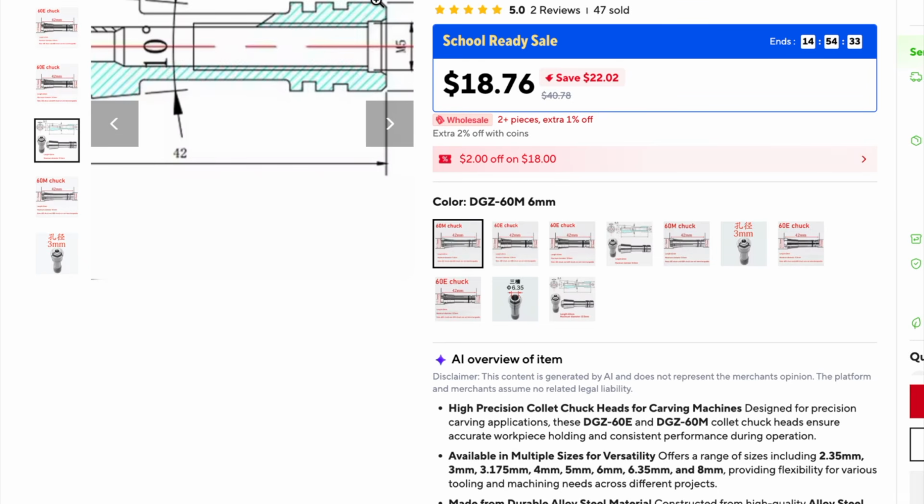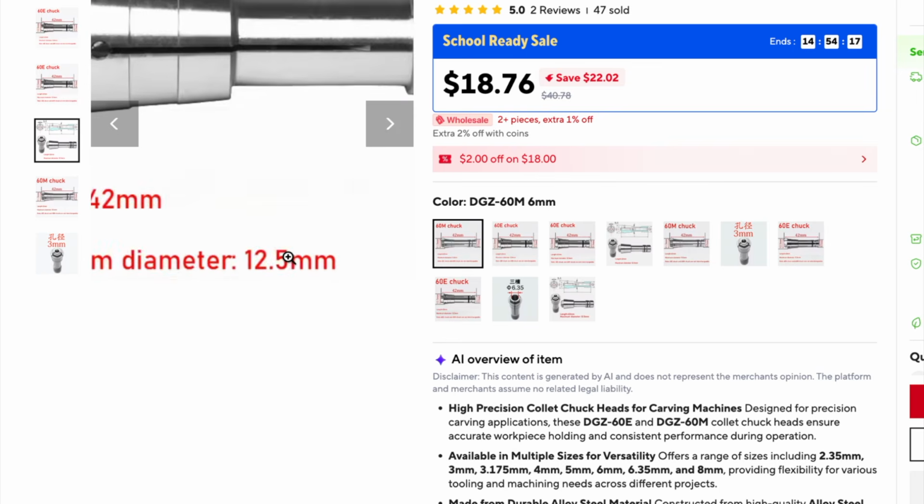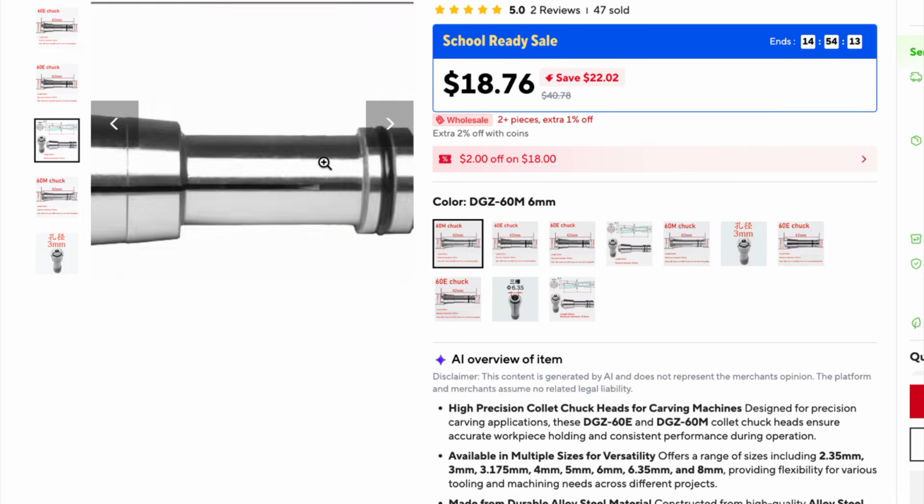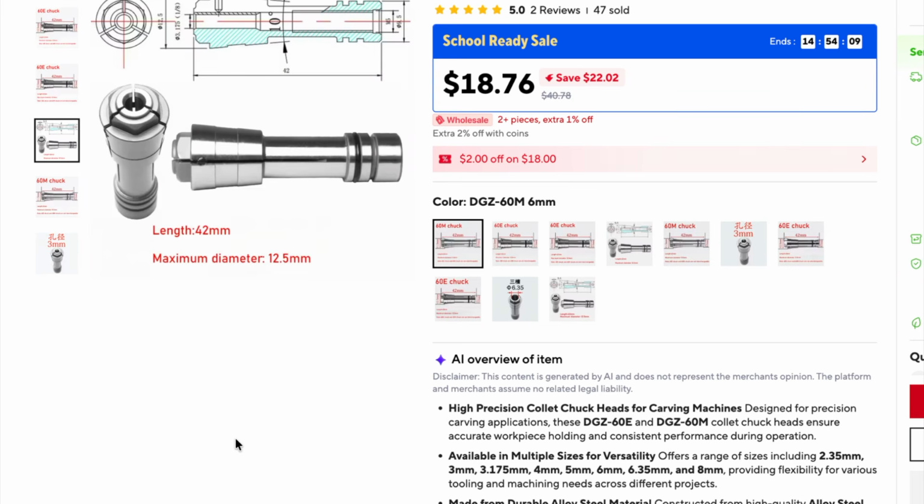That's about 1 inch. So if you get a 1/4 inch tool, you're supposed to be 3 times the diameter max stick out, roughly. That's 3/4 of an inch. So if you get a 2-inch overall tool, you're already sticking out past that. So you've only got basically 1 inch that the tool can go in the spindle, and the rest of it's going to hang out by design.